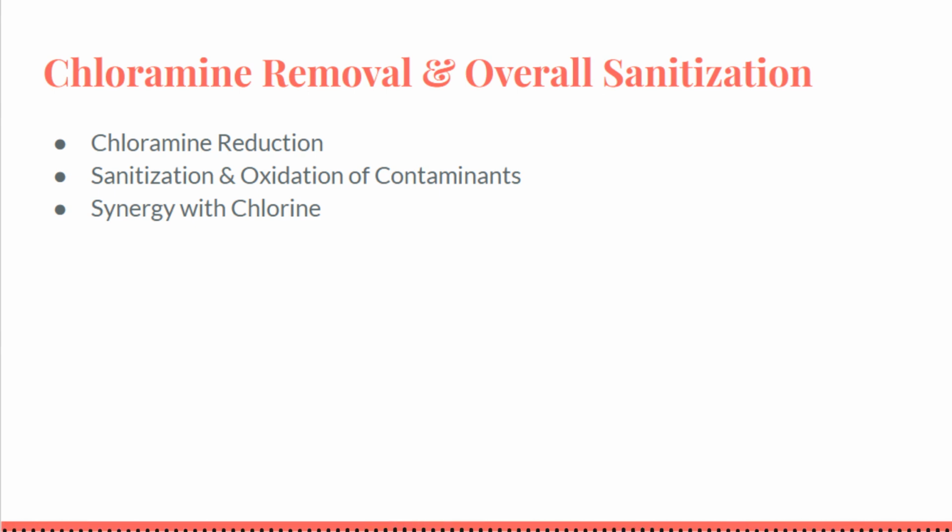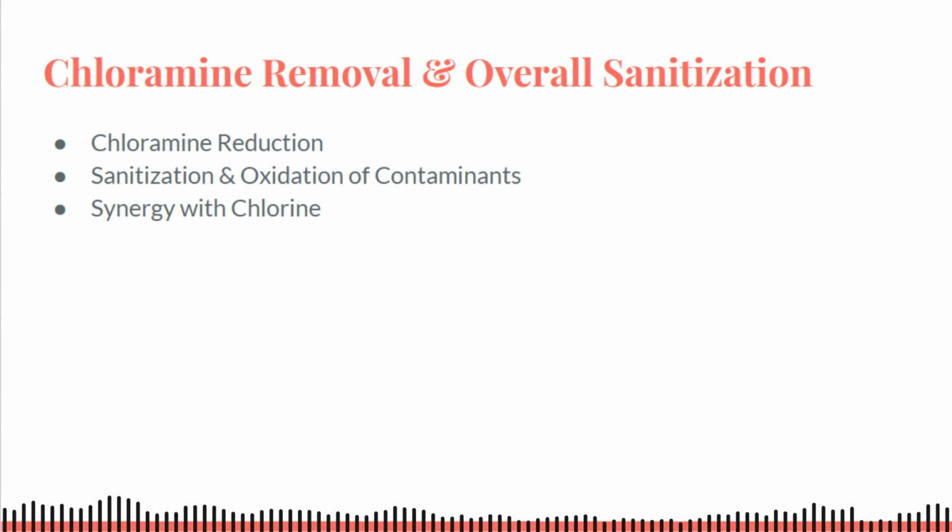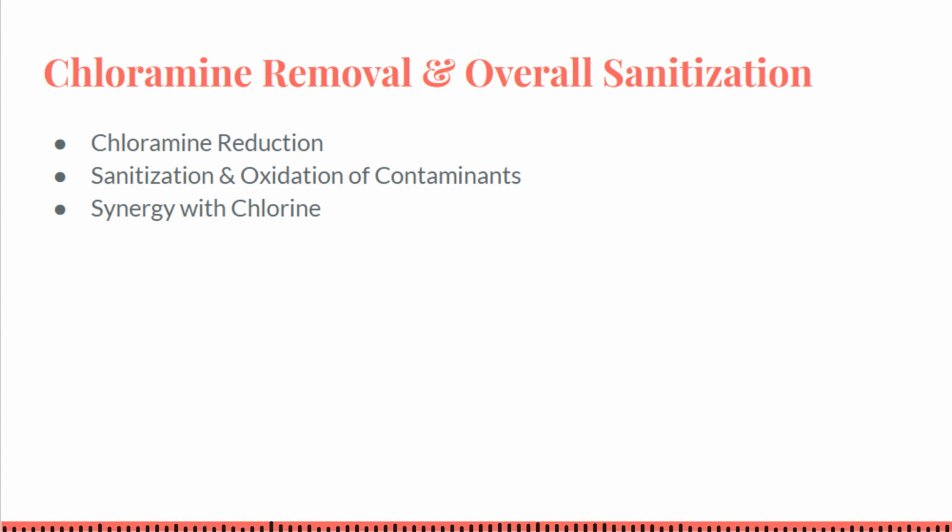For instance, AOP can oxidize organic matter in seconds that would take chlorine days, meaning the chlorine-free residual remains available longer for killing new germs. AOP in particular helps chlorine work better by aggressively breaking down chloramines and other intermediates. Pool owners often find that with ozone or AOP, they can run at the lower end of the recommended free chlorine range, yet still have sparkling, odor-free water.